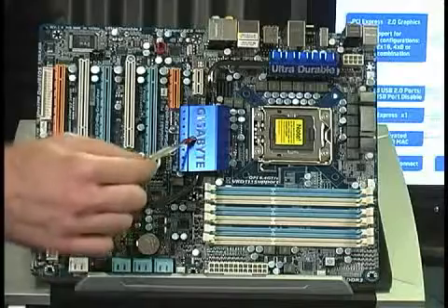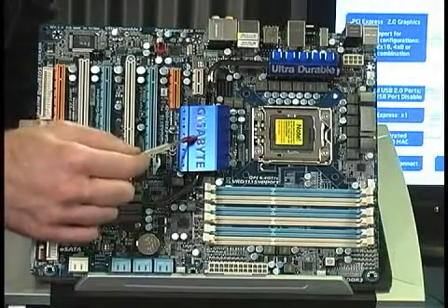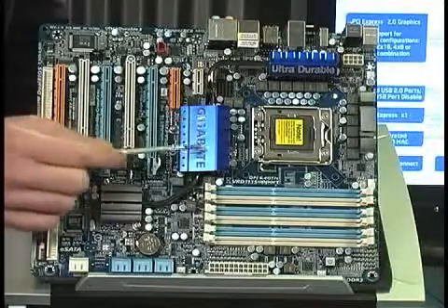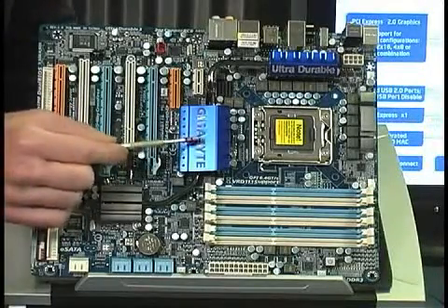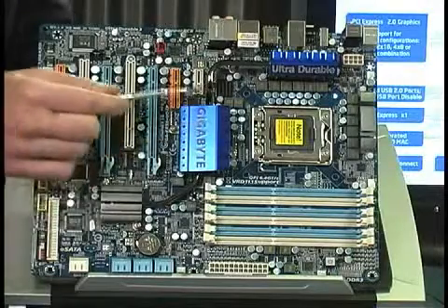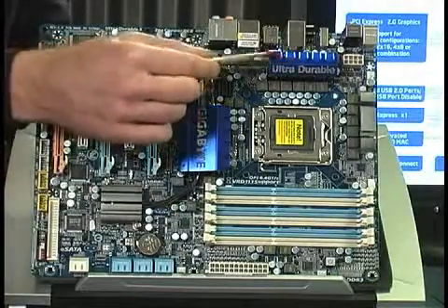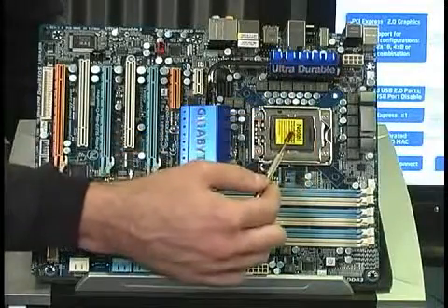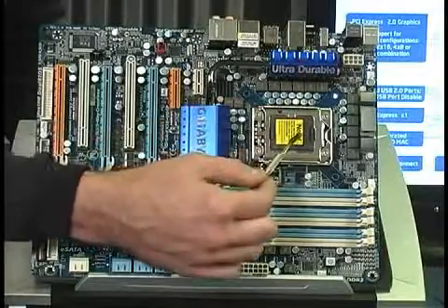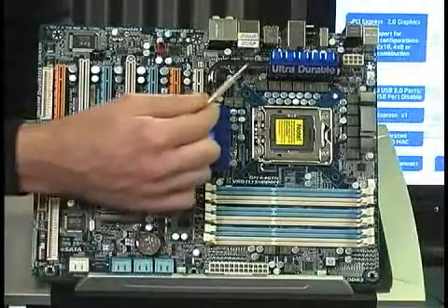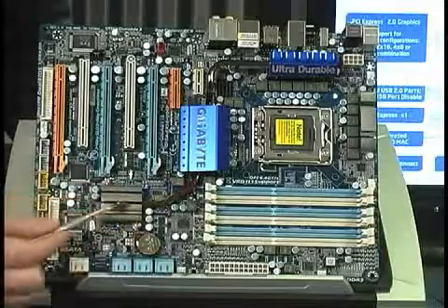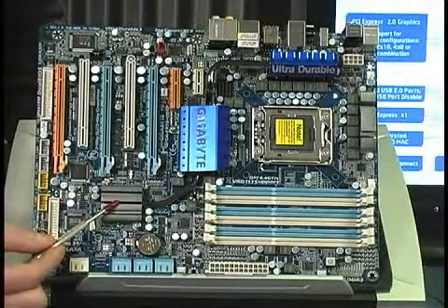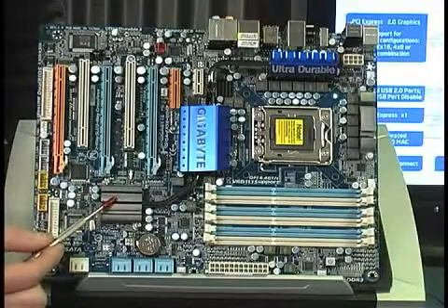Now, Northbridge chips in modern systems tend to run hot, so in most cases you will find some sort of a heat sink on them, as you see here. Now, this heat sink is a fairly advanced heat sink. It has what's called a heat pipe that helps distribute heat among voltage regulators here. This is voltage regulator circuitry for the processor. It basically provides power to the processor. Then we have the heat pipe connected again to the Northbridge, and then over here to the Southbridge. This is the Southbridge component, also under a heat sink in many modern motherboards.